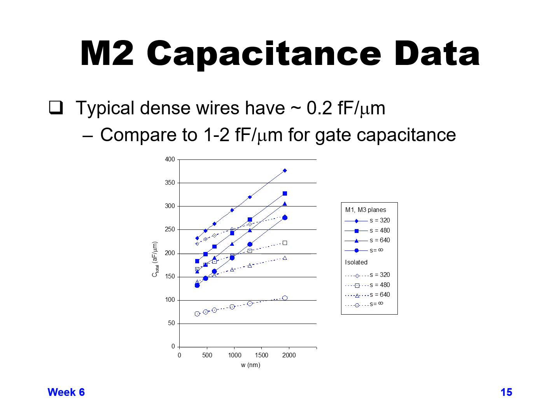It might sound like it's a lot less, but your wires tend to be a lot longer than your gate size is, and so you can see where you could wind up having your metal wires add up to the same amount or even more than what your gate cap is, depending on how many things. If you have a large fan out, you're going to have much more metal, and that metal could wind up adding as much capacitance as the gate caps of your fan out. So wire can have a significant effect on your overall load that you have to drive.